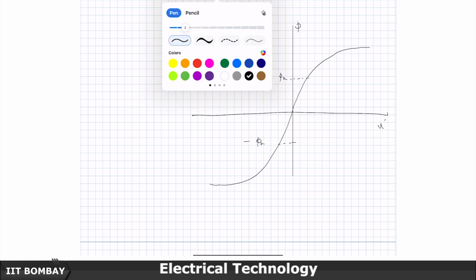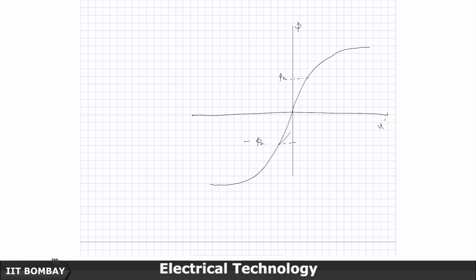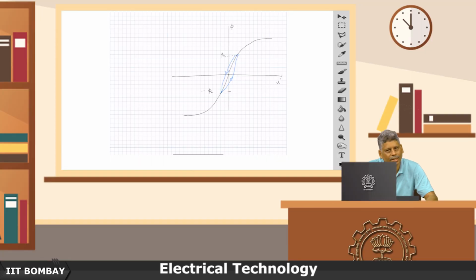Then the curve that you are going to actually see is this, due to the hysteresis effect that we have already discussed earlier: there are domains or grains in the iron, and they need to be aligned, and that requires work to be done, and that work has to be dissipated as heat, and that leads to some remanence. To get the flux back to 0, you actually have to apply a demagnetizing current, and so on.